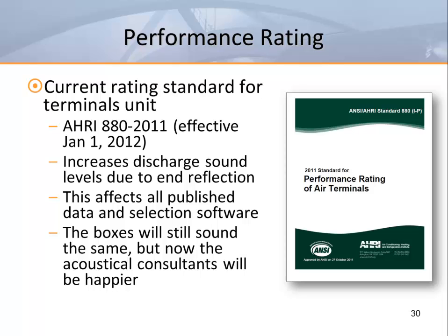This is sound energy that cannot be read by the microphones in the test chamber, but it must be accounted for. An AHRI research project, RP1314, completed in 2008, provided a means of calculating end reflection based strictly on the discharge duct dimensions. According to this latest standard, all manufacturers must calculate end reflection and add it to the discharge sound power levels of all terminal units.